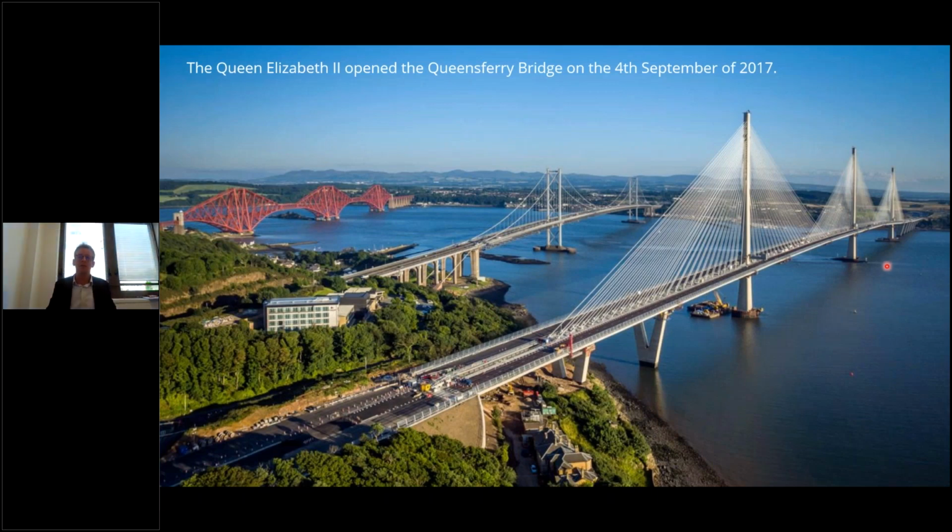So that's the end of my presentation. Jerome, we have a question I noticed. How do you model the steel mesh panels with PLAXIS 2D? Yes, so it's quite easy actually. We use a GeoGrid option. So we use GeoGrids to represent steel mesh panels, and we adjust the axial stiffness of the GeoGrid elements to represent the stiffness of steel. So GeoGrid elements with the stiffness of steel.